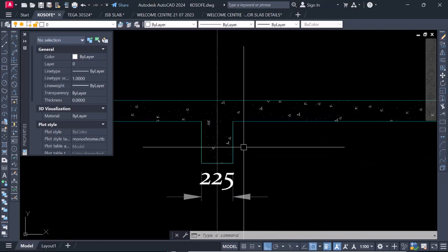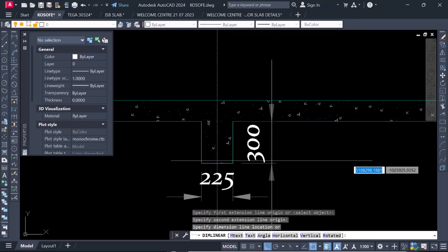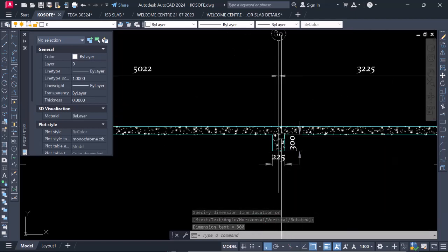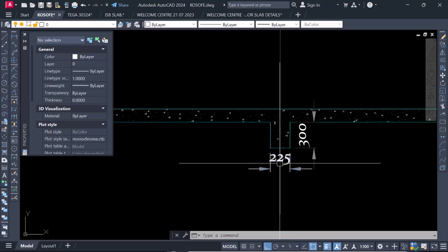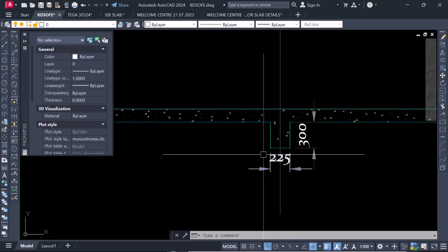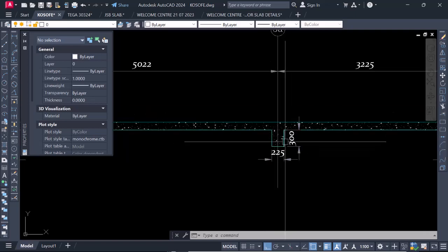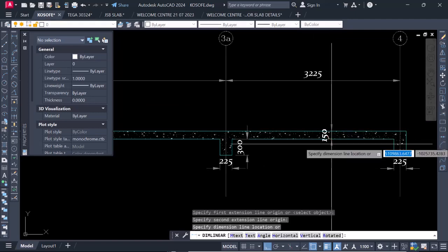You can still detail this, and see the drop down. It's basically for formwork. Somebody doing his formwork will understand that he has a nominal depth of 30, and is going to have his bottom, so they can prepare his bottom soffit. For the beam soffit, you're going to prepare these, and this will be the drop before you have the overall slab thickness of 150.